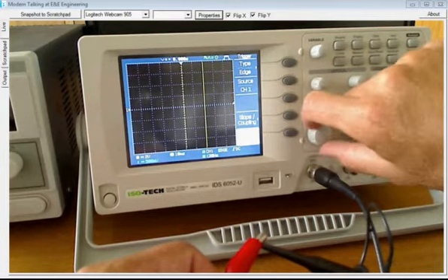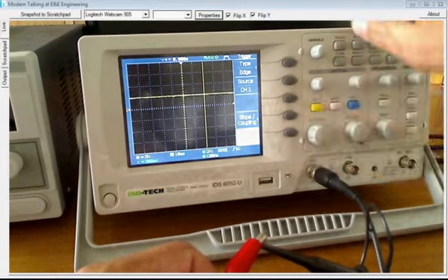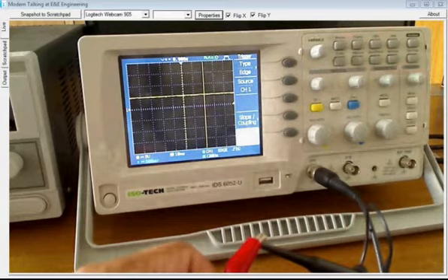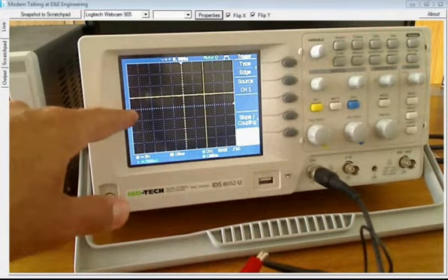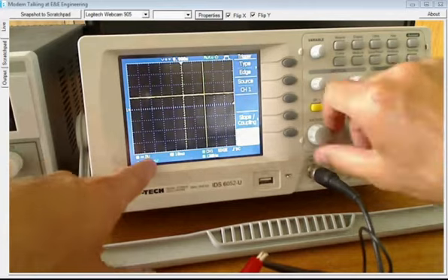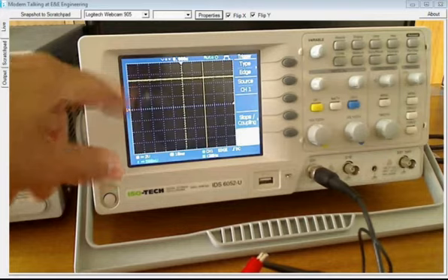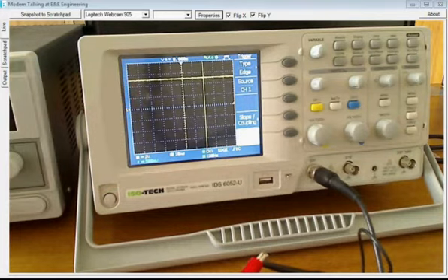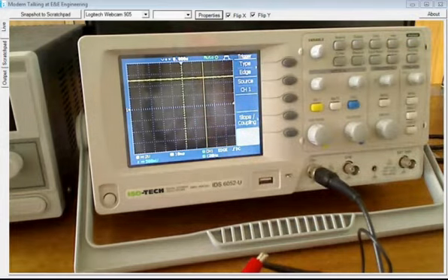to have, I'm expecting, I guess, about 2 volts per division will show it to me. There we go. So that line there tells you that the voltage that I'm measuring is 1 block away from 0, and each block is 5 volts. So let's just change that to 2 volts, measure again, it's 1, 2.5. 2.5 blocks is the voltage level that I'm measuring, which relates to 5 volts.